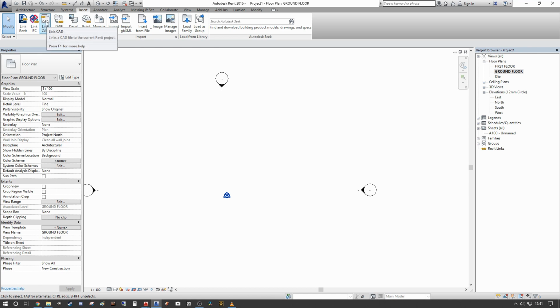The important thing with the link CAD is it works similar to an old AutoCAD XREF, whereby every time the project reopens, the most up-to-date version of that drawing will reload, as long as the file path has remained consistent. So link CAD is a great way of staying on top of various revisions of CAD files that may have to be worked upon as the project develops. Import CAD has its uses, but it also adds to the general file size and sometimes even interacts with the geometry, so we only use it in very particular cases. So rule of thumb, when in doubt, link CAD only, okay?